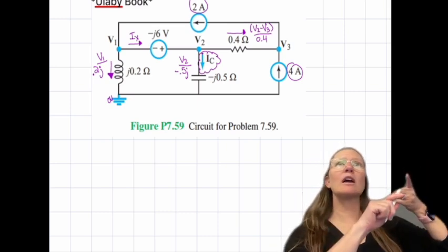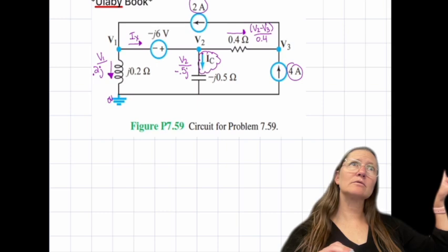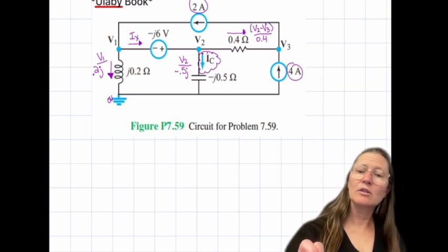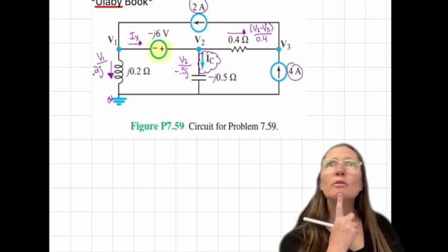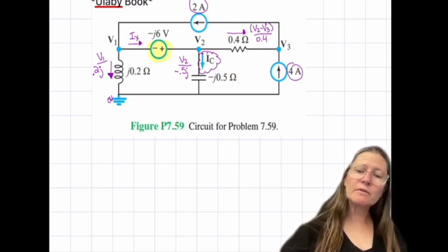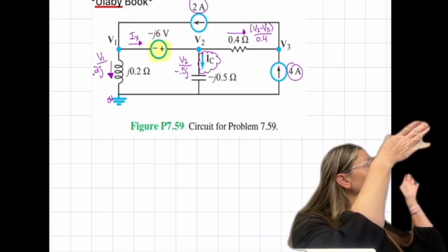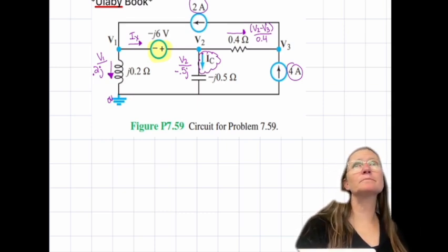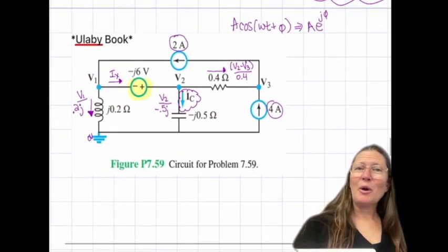Because we've introduced that IX. So where do we get that 4th equation for IX, or related to IX? From the known voltage source, right? So we put it in terms of that value. We know V1 is going to equal that value, and that will be our separate equation. Okay, now work on it.